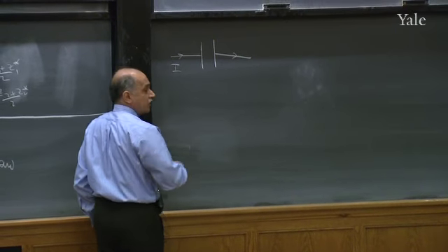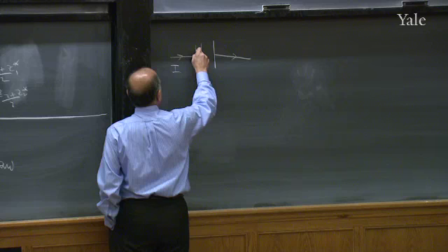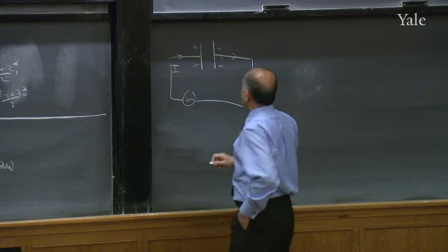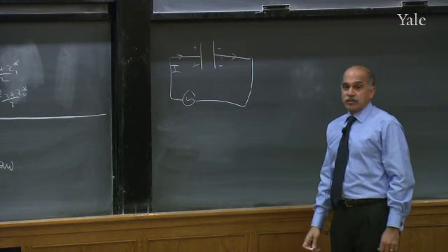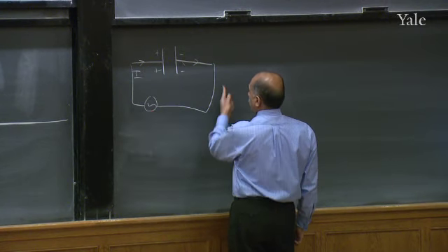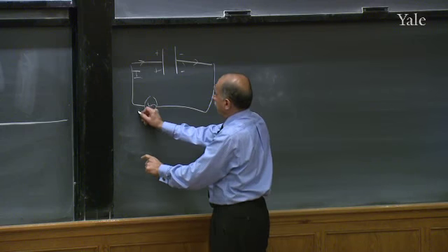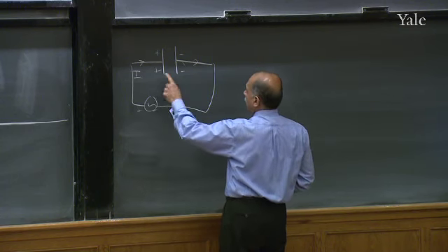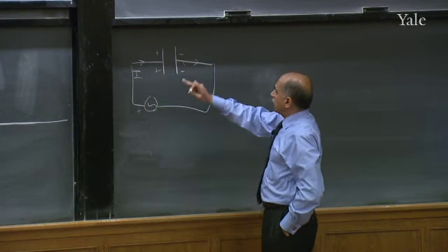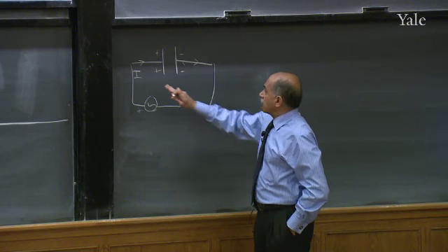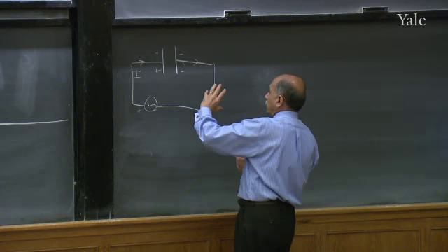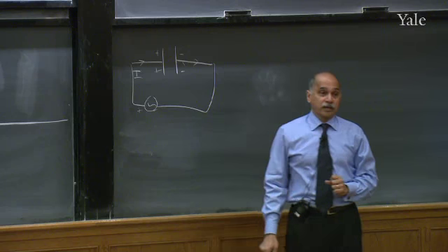When I say flowing through a capacitor, I hope you know what it means. I want you to be very clear about this. Suppose you connect it to some AC source. Nothing really flows through the gap in the capacitor. It's not possible. What happens is, for a while, plus charges rush here and minus charges rush to the other plate, because that's the polarity of my AC source. Later on, it's reversed. Then minus charges go here and plus charges go there. So there is an alternating current in the circuit, but there is no current flowing right through in one sense. But there's nothing to keep it from going this way and that way, because they don't have to jump the gap to do that.